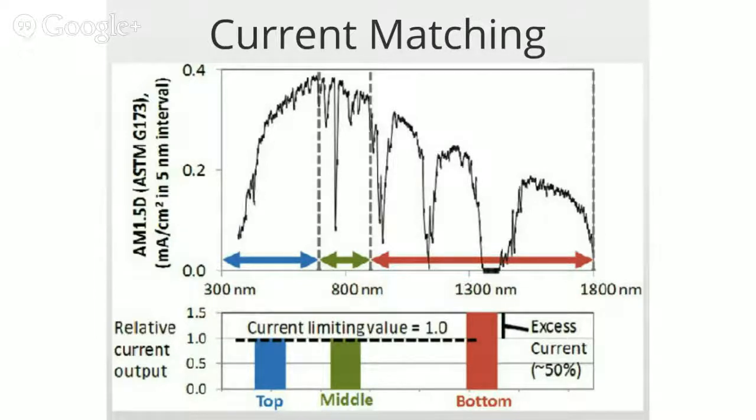In this case, you cannot independently operate all three cells at their maximum power point. There's no way, because they're all connected in series. They all have to draw the same current.